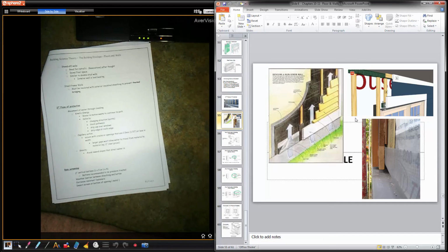People have to think. We're not putting wood in place necessarily just to install vinyl siding. We are, but we have to make sure we don't trap moisture while we're doing it. So don't put a piece of wood in place until you've thought about whether there are any dangers there. The best way is just to keep things vertical. Keep water running downhill. If you're stopping water, you've got to find some way of getting that water out. So if you're stopping water on top of a window, you have to find a way to get that water out.